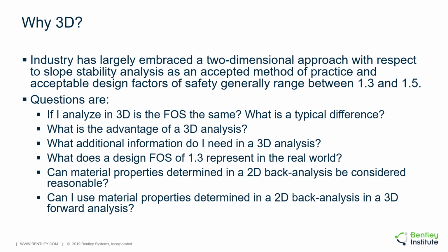So just to couch this presentation, industry has largely embraced a two-dimensional approach historically with respect to stability analysis. And we have accepted design factors of safety generally ranging between 1.3 and 1.5. But this typically brings up a lot of questions in doing the analysis.